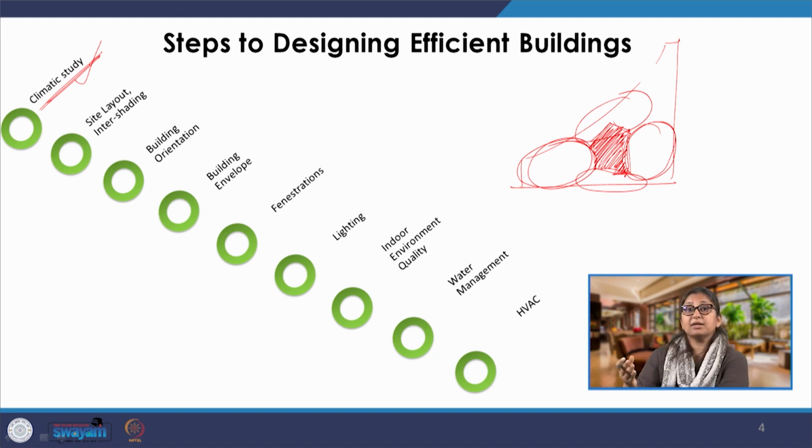And if you look at the traditional buildings which are there, if you look at the classic examples, we will see that difference being evidently clear. We have a different type of building for hot dry, we have a different type of building in warm humid. If you go to Kerala, you will find that the buildings have ample opportunity for air to be ventilated in. Huge windows, verandas which cut off the rain, but allow the wind to move through in the spaces, and the buildings remain absolutely comfortable. Narrow courtyards which allow ventilation to happen throughout the day and night.